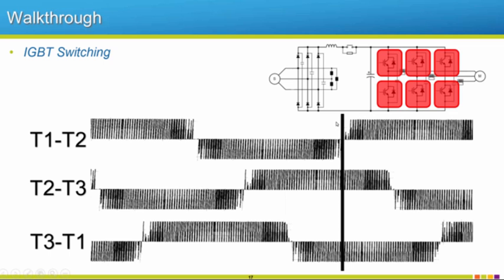So you notice that for these, now it's just the bottom IGBT firing, and then through here, for the second one, so these two, you're going to notice that it's the negative portion, and then the upper one will start to fire. And then so on for the third phase. So I think that shows pretty good how that switching happens. If you notice that these two never fire at the same time. If those two fire at the same time, that's not going to be good for your system. So there's usually this little bit of off time where we make sure that both of those don't fire.